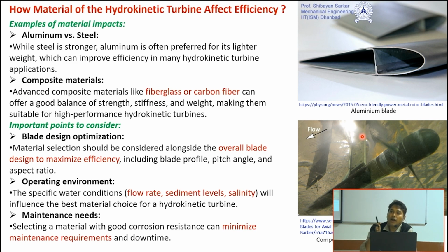Basically, we provide a particular aerodynamic shape to a turbine blade. So to get this shape, whether the selected material will perform best or not, and whether the manufacturing technique we are adopting gives us the freedom to make that type of shape or not, those are the criteria.